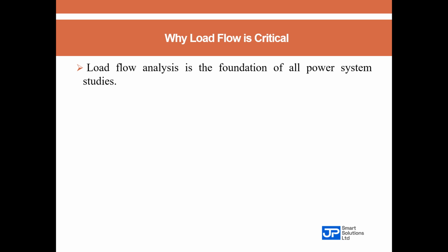You must carry out a load flow study to determine what is the problem with this system. Then and only then can you carry out an optimization study. You can determine an optimization approach to use on the power system network. So load flow analysis is actually the foundation of all power system studies.